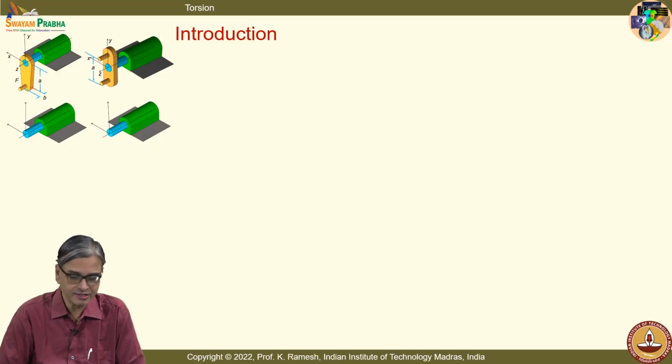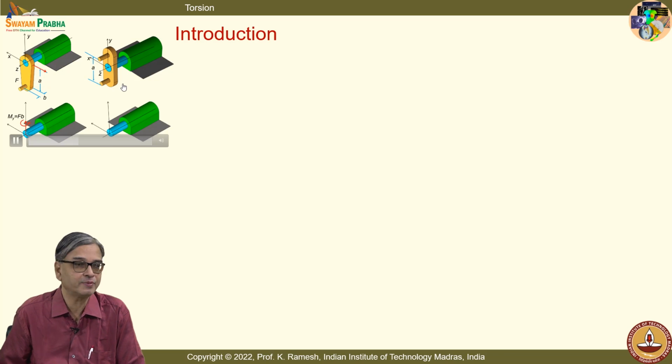And before we get into this, you will also have to bring back your old memories on how you understand what is known as a coupled force system. See, if I have a coupled force system, when I look at the effect on the shaft, you get only a twisting moment. You get the idea? On the other hand, if I rotate the same shaft with a single arm, I get the rotation. In addition, I also have another moment and also a force acting on the shaft. So, there is a subtle difference.